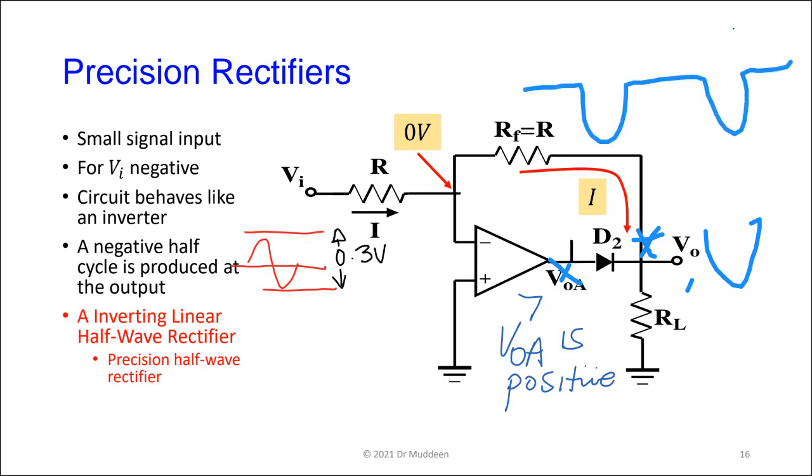And remember, I said if I put 0.3 volts here, so this is going to be 0.3 volts here, and you have nothing coming above it. Right, so the fancy name for it is an inverting half-wave rectifier, but it is in fact working as a precision half-wave rectifier. So we clear on that? Make sense? Excuse me, sir, question.